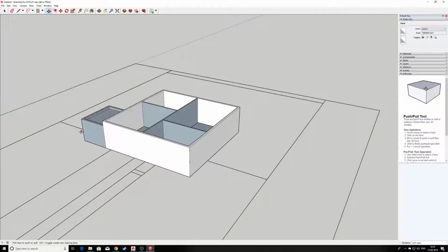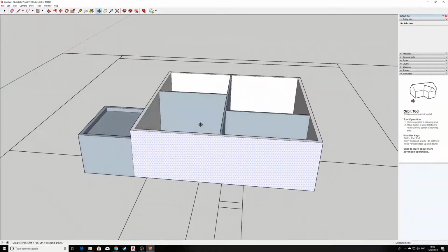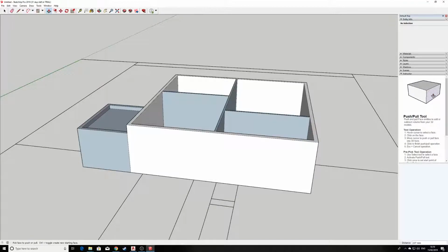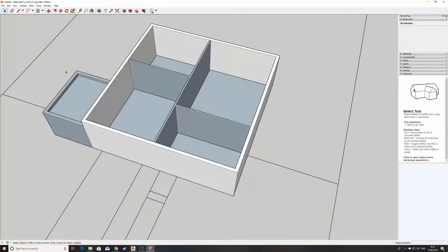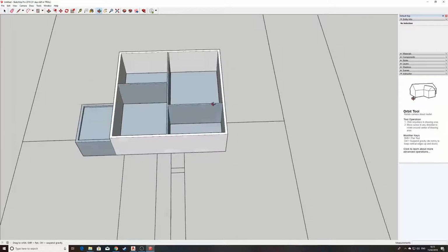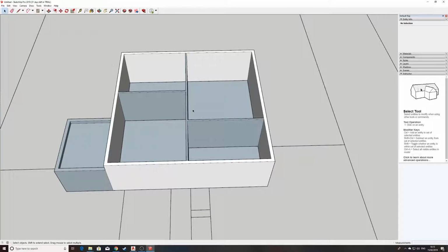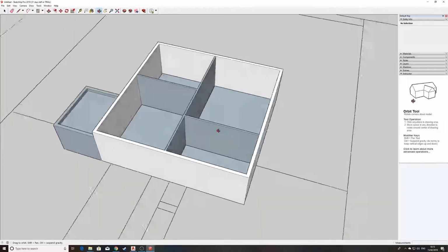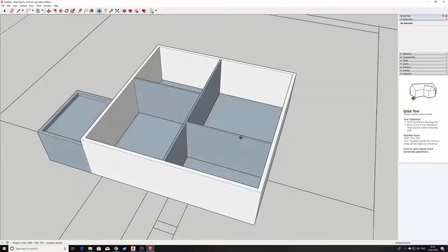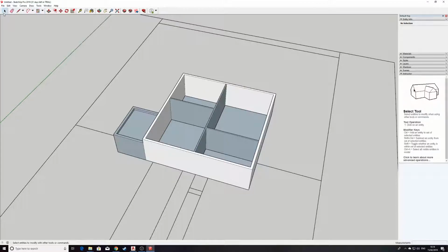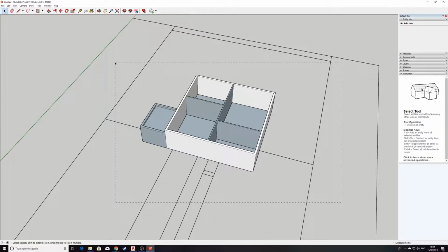Okay. So next we'll move on to the roof. Just for modelling the roof, the next stage that we want to do is draw a flat plane on top of these exterior and interior walls. Now, a common kind of problem that you'll find is if you just try and draw a rectangle over the top, it doesn't show up.